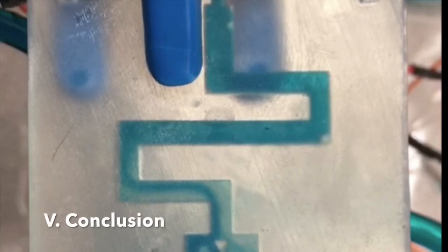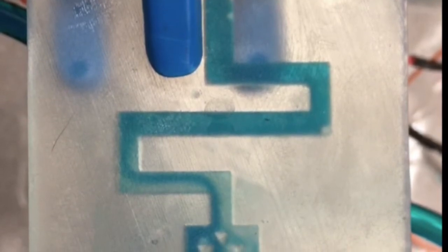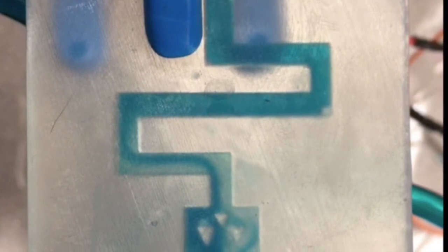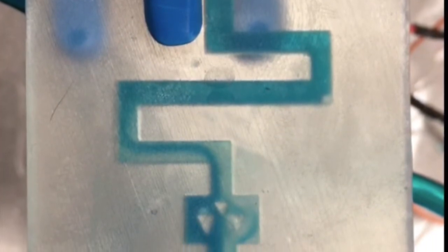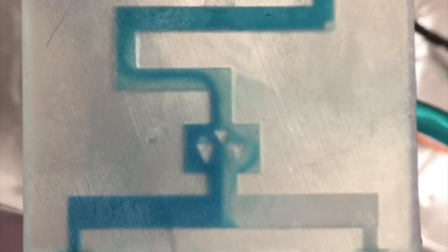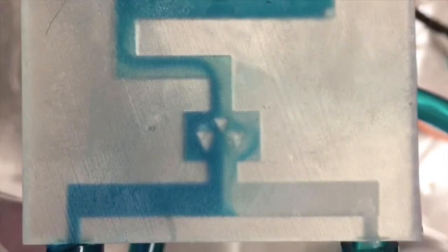In conclusion, we can see that our first custom reactor design was our best reactor design, featuring a 70mm channel length and baffles, promoting the best diffusion of all our reactor types. The T reactor featured the worst diffusion among all of our reactors, with a small 35mm channel length and no baffles at all. This is in agreement with the limited COMSOL simulations we were able to run, as well as the theory for this experiment.